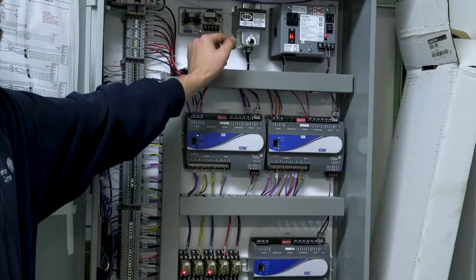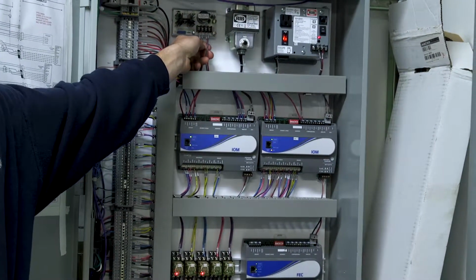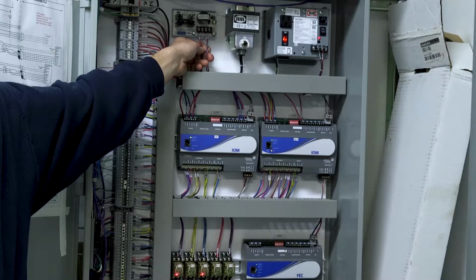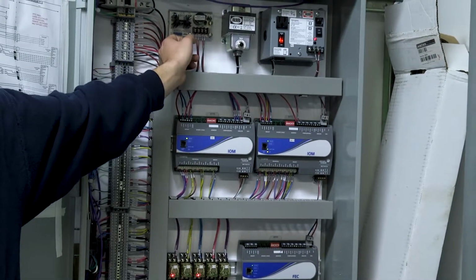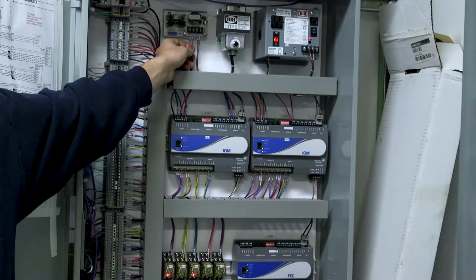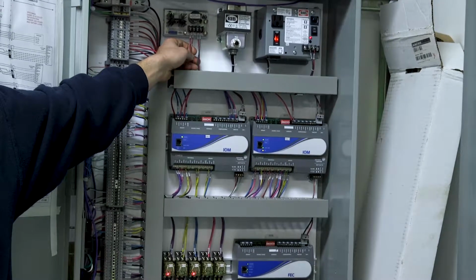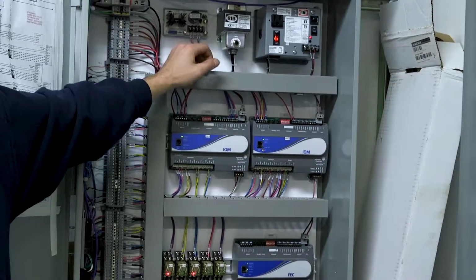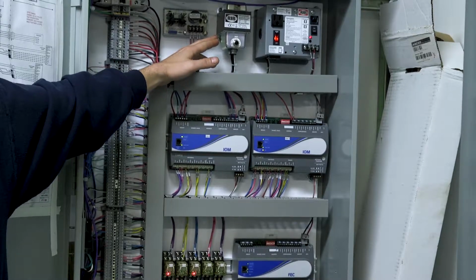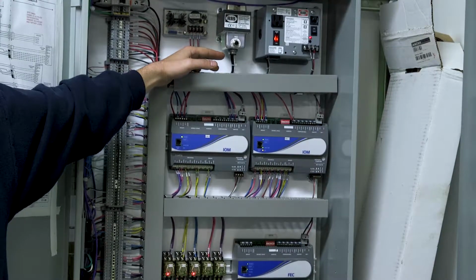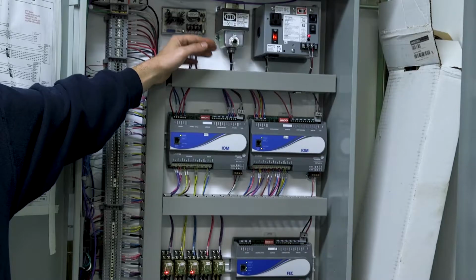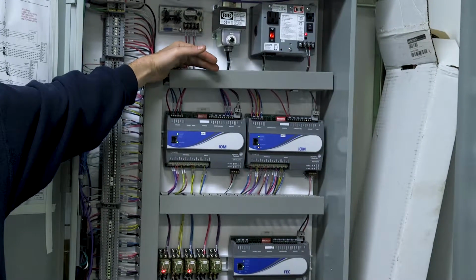This is your rectifier. This is what we're using for our DC power. So anything with a 4 to 20 milliamp signal will be coming off of this. So for any reason if any of your temperature sensors or anything like that go out, you want to check to make sure that this is good or this fuse isn't blown. Because a lot of times when you see multiple temperature sensors go out, it's because your rectifier went bad or a fuse blown.